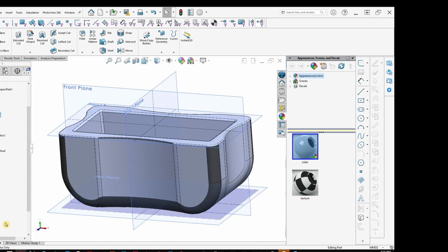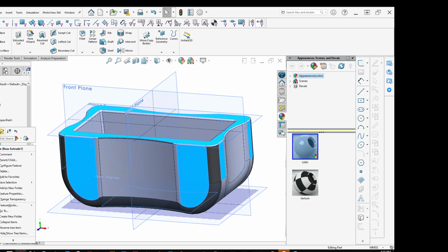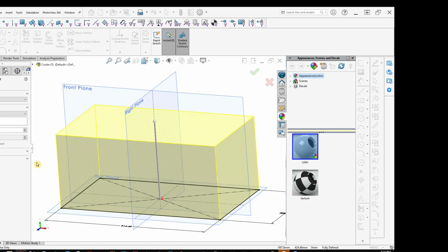what we can do is, at the very, very beginning, because sometimes you can add draft to your model at the beginning or you can add it at the end. When it comes to bosses and ribs, that's one of the last things I do, just because it's a final detail that doesn't necessarily need to be shown at all times. So you can come back in, we'll edit this. We know that it's rotational molded. We know that we've got a texture on there. We know that it is 2 feet deep. I've done my Google research, and Google tells me it needs to be 2.5 millimeters. And you're going to see how this changes things.